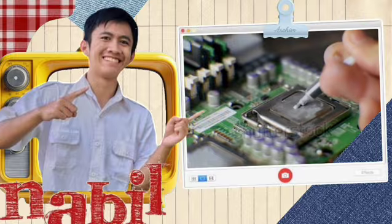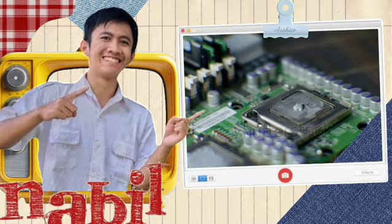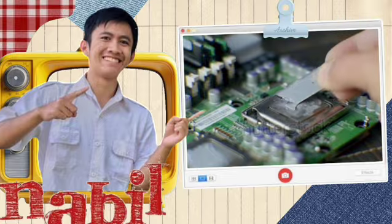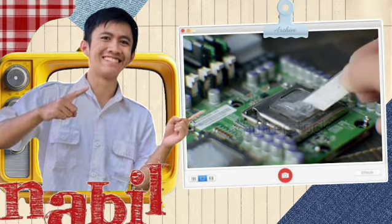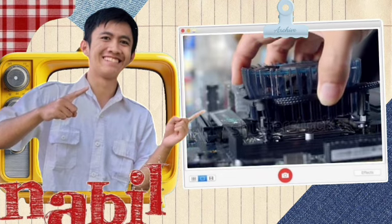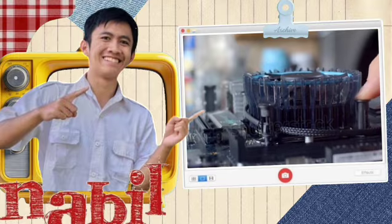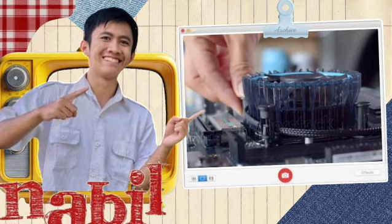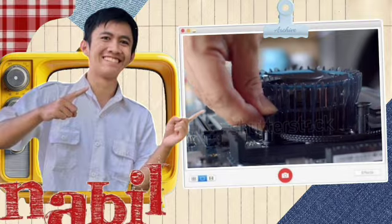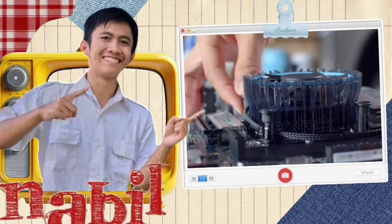Step 3. Applying thermal paste and mounting the cooler. Now, apply a small pea-sized drop of thermal paste onto the center of the CPU. Then take your CPU cooler, either the stock one or a third-party model, and align it with the mounting holes around the socket. Press the cooler gently into place and secure it evenly with screws or clips. Finally, connect the cooler fan cable into the CPU fan header on the motherboard.